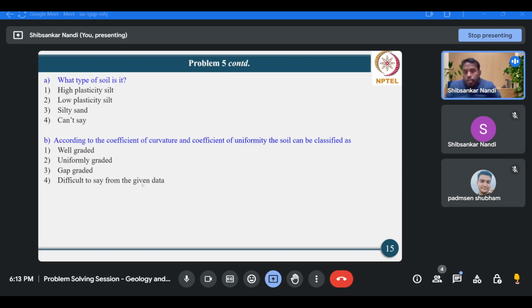Now I hope this part is not covered completely. From this week, that is week 2, we'll be learning about the classification of soil. So we'll be answering these two questions in the next week. But before that, whatever calculation is needed to answer this type of question is already known to us. We are familiar with that calculation, meaning how to plot the grain size distribution curve, or how to calculate the percentage finer corresponding to a particular sieve size or particle size from the hydrometer analysis.